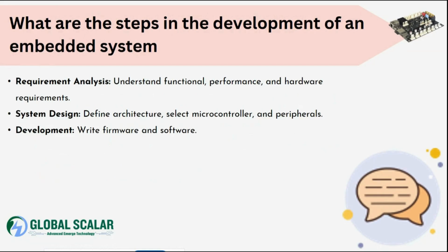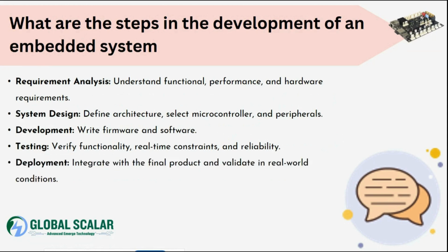And then we develop the hardware and software accordingly, and in the case of firmware, we usually write the firmware in a low-level language, and then comes testing. We need to verify whether the functionality is working and whether the timing response is right. Then deployment: we integrate with the final product and validate in real-world conditions.